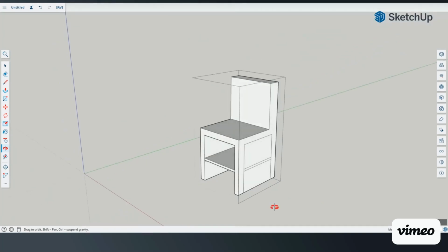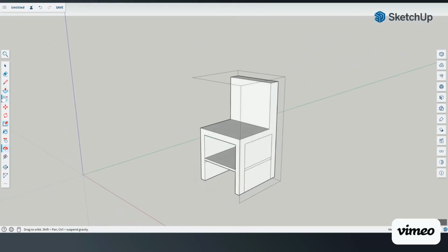So now we're going to go ahead and get rid of our middle sections here. Again, using that push-pull, I'm going to just push this out a distance. I may need to go in with my select tool and just delete off that face as well. And I'm going to repeat this for my bottom half. Again, using my selection tool to go ahead and delete off that face. I even can delete the line at the bottom.